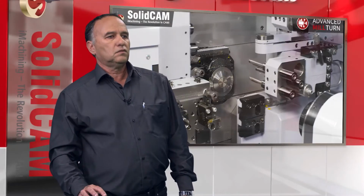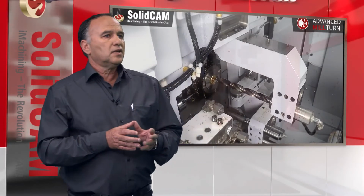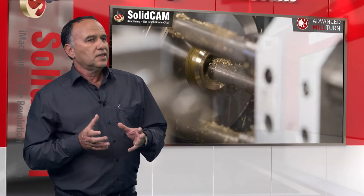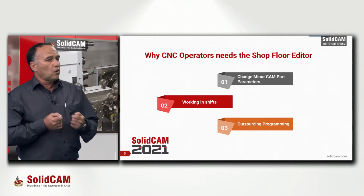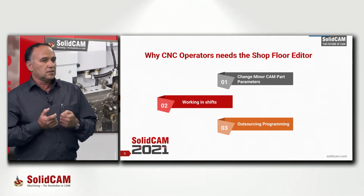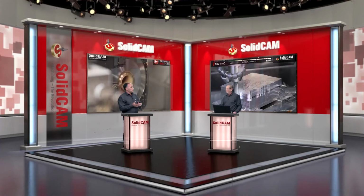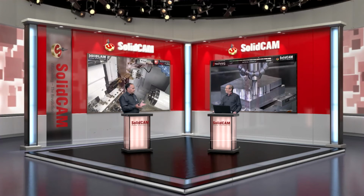Okay. Now, Zvika, let me ask you, why does the setup operator need the shop floor editor? Well, there are a few reasons for this, Sidney. First, change minor SolidCAM operation parameters. Sometimes, the CAM programmer is new to machining or has less experience than the machine operator. The shop floor editor gives the shop floor personnel the flexibility to make minor changes to improve the operation process. Another thing is working in shifts. Sometimes the machine operator works on a different shift than the CAM programmer, or the CAM programmer is not available at the exact time to make changes.